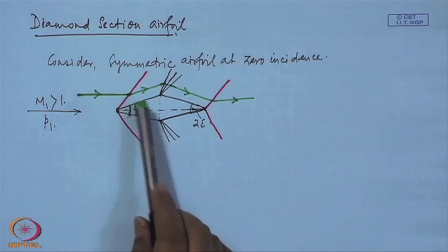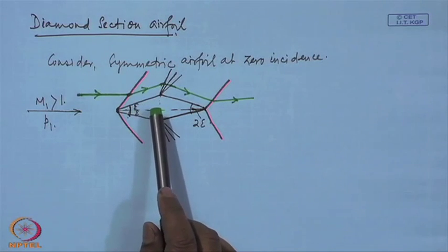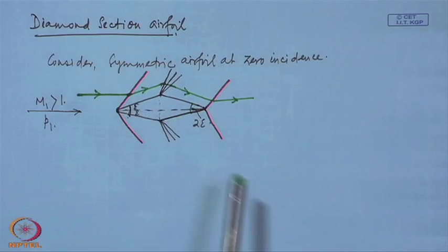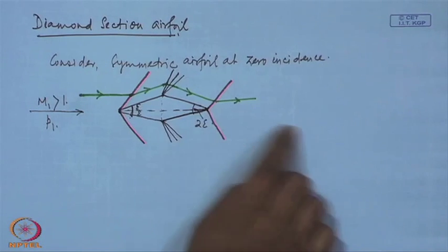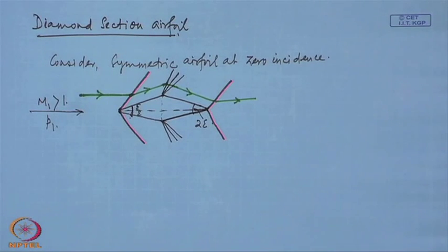However, if there is asymmetry in the geometry which will cause asymmetry in the flow, then there will be a slip stream from the trailing edge whose direction will be determined by the total turn that the flow undergoes on the upper surface and on the lower surface.